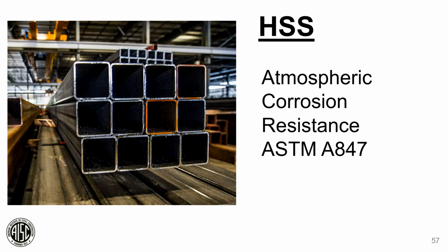When you're dealing with atmospheric corrosion resistance, HSSs have their own standard. That's A847. So you don't use the A588 for HSS shapes. It's ASTM A847, a totally different ASTM standard for atmospheric corrosion resistance. And you may see HSS being used in pedestrian bridges for this application.